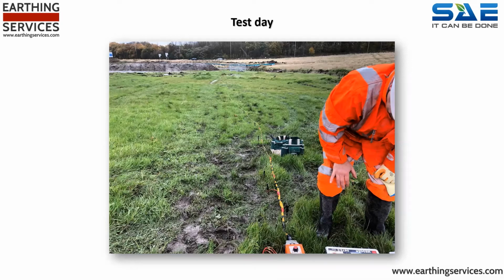Whilst the testing stage is notionally the main event, without thoroughness at each stage leading up to it, and indeed following it, the soil resistivity survey data may be insufficient to confidently specify an effective, safe electrical earthing system. Follow the method, keep the cables in a straight line as far as possible, make sure your test probes have good contact with the ground, and you should find it provides a solid data set. Once you have done a couple of these tests, you realize how easy they are and how beneficial the data it provides is. We will be moving on to processing data in a moment.